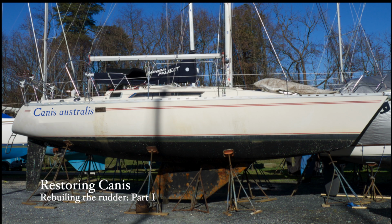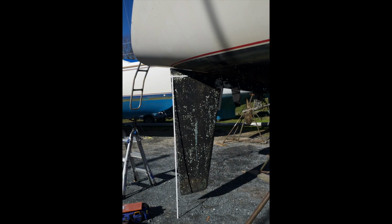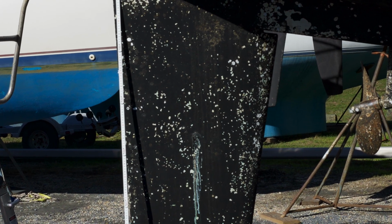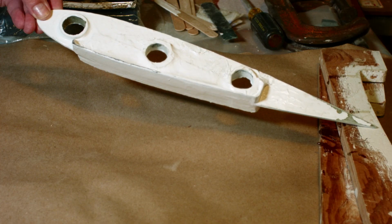Canis' original survey revealed several problems: a rusted keel, blisters on the hull, keel bolts badly needing replacement, and a weeping rudder. From this list, I gave the yard the hull and the keel jobs, and left for myself the rudder and the keel bolts. At the time, I thought all that was needed was to drill a couple of holes, drain the water, and patch the holes. Needless to say, it took a bit more than that.